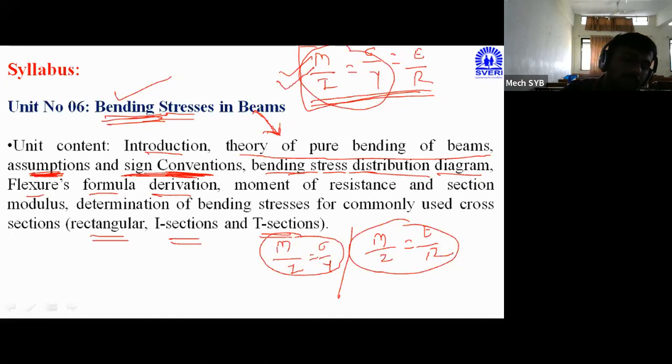And if you look at this particular formula, हा formula जर तुम्ही बघितला bending moment चा, M upon I is equal to sigma upon y. So maximum times this combination we are going to use for our calculation. हे जे काय पहिली दोन कॉम्बिनेशन आहेत, M upon I is equal to sigma upon y. So what is this particular M?